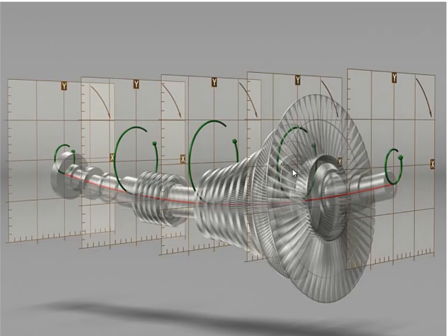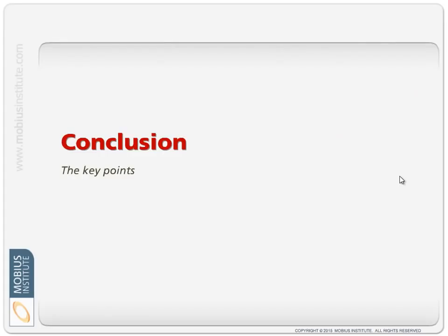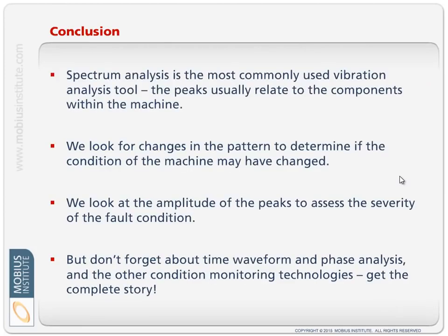Now we may not be able to put proximity probes in all these locations. I'm just showing this for illustrative purposes, but this is the orbit, and that orbit tells us it may be small and circular, that's good. It may be bigger and elliptical, and then we have to start to ask, well, is that okay? Could it mean there's some preload or misalignment? If it gets big, then it could be the oil whirl we just looked at, or oil whip. So there's lots of things we could talk about with all these topics, but what I'd like to do is just summarize what I think are some of the more important points.